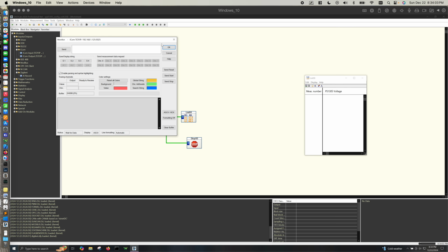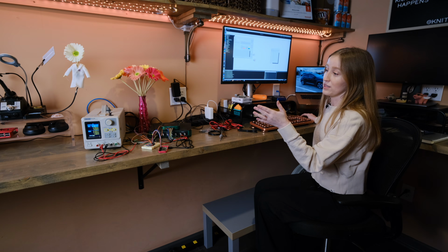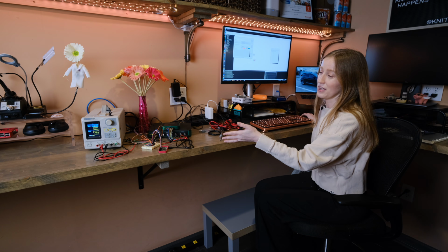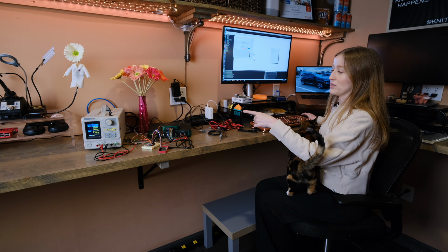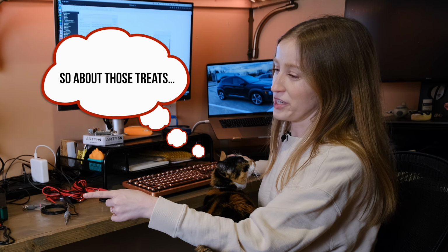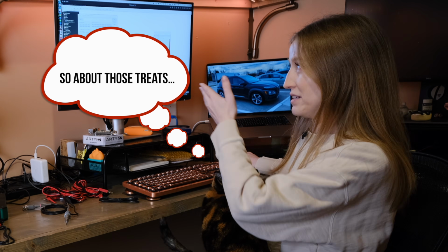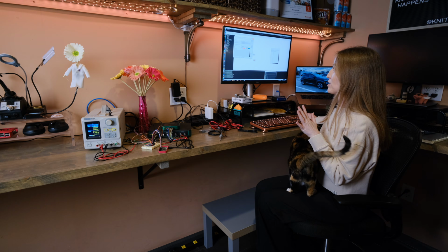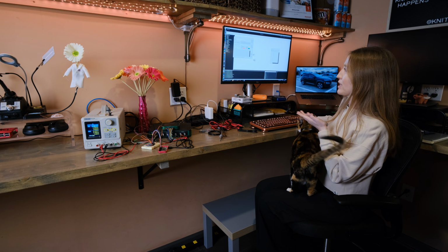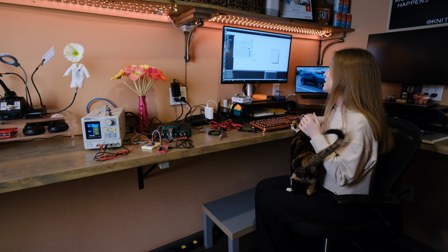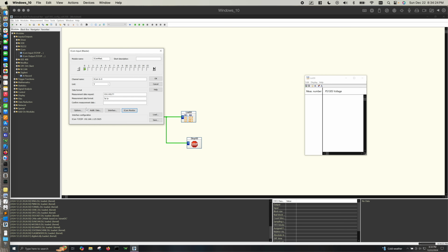I discovered this because when I had the start command set as the turn on channel command, I noticed my output was turning on unexpectedly. The monitor sends the start command every time, even though it has a manual send start here. So just a quick thing to look out for.